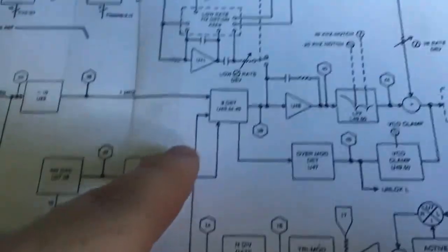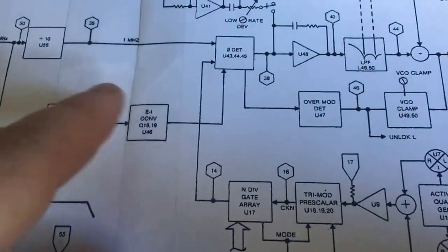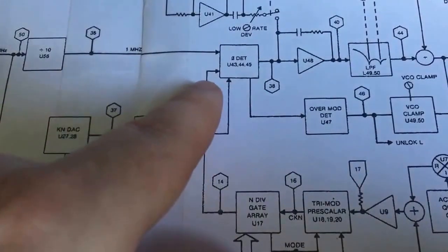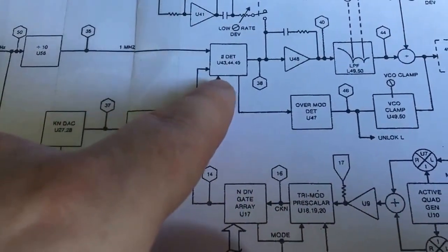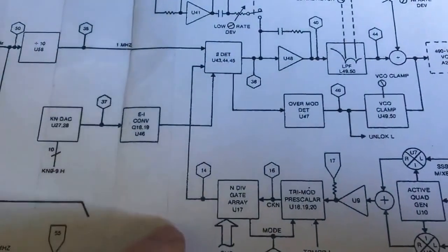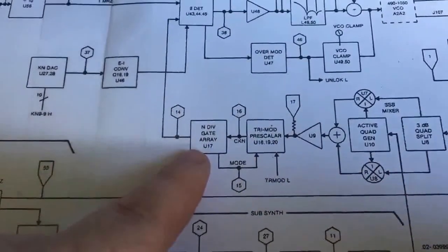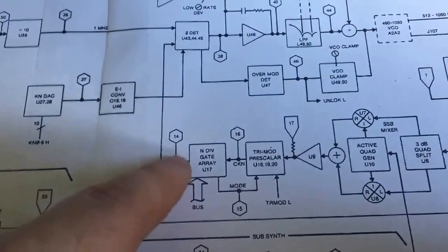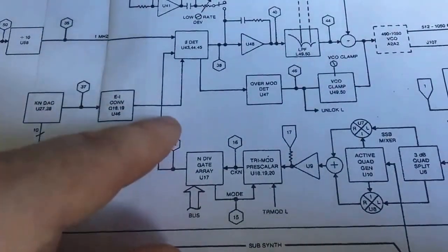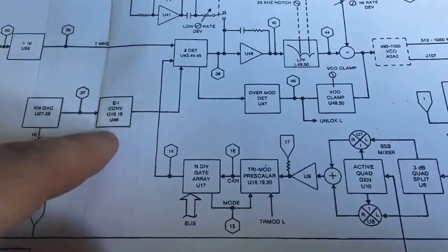But by pulling the ICs out, I did that in a video a few days ago. Well, probably part of the same video I'm doing now, earlier in the video. The phase detector is where it seems to come back to. Or this U17 gate array. Because this phase detector is detecting those 1 megahertz there and the 1 megahertz from here. So